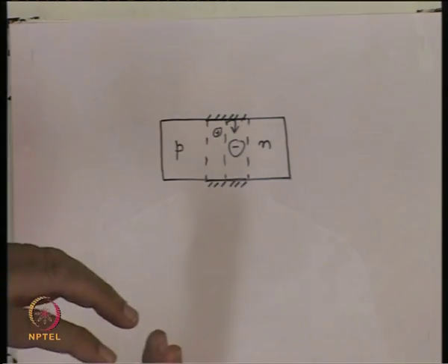So, in fact, by making the fabrication of LED in such a way that I have some kind of reflecting boundaries which will make the photons confine for a longer time inside the depletion region, the same LED can be converted into a laser. So, in principle, a forward bias p-n junction made of a direct band gap material with proper polishing of the surfaces, so that the photons can be trapped, will act like a laser.